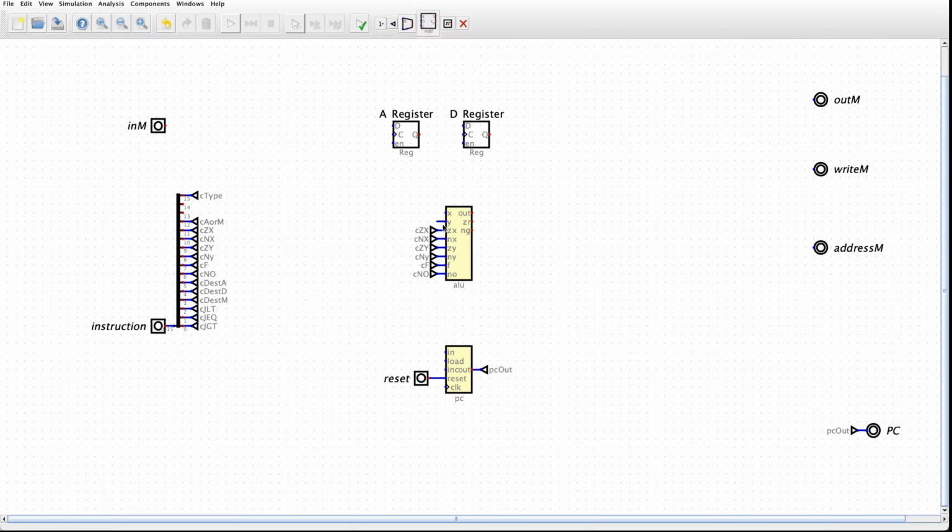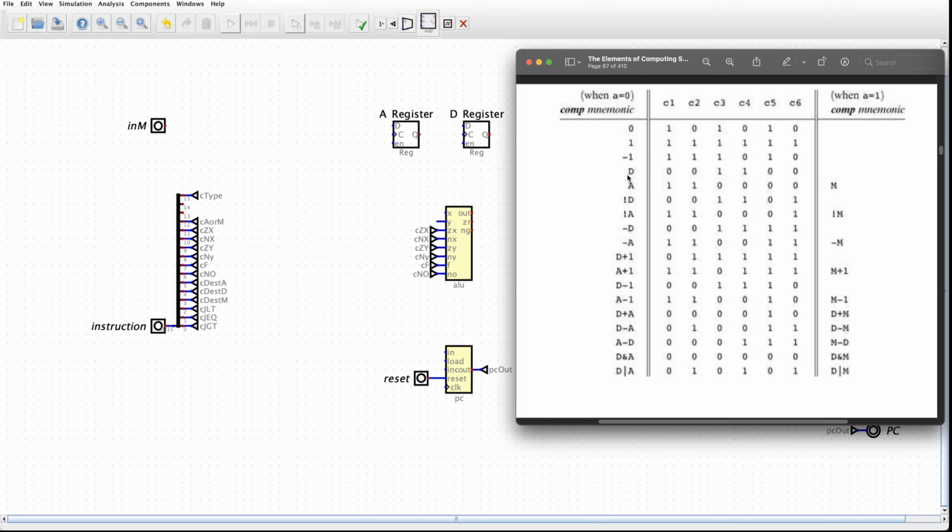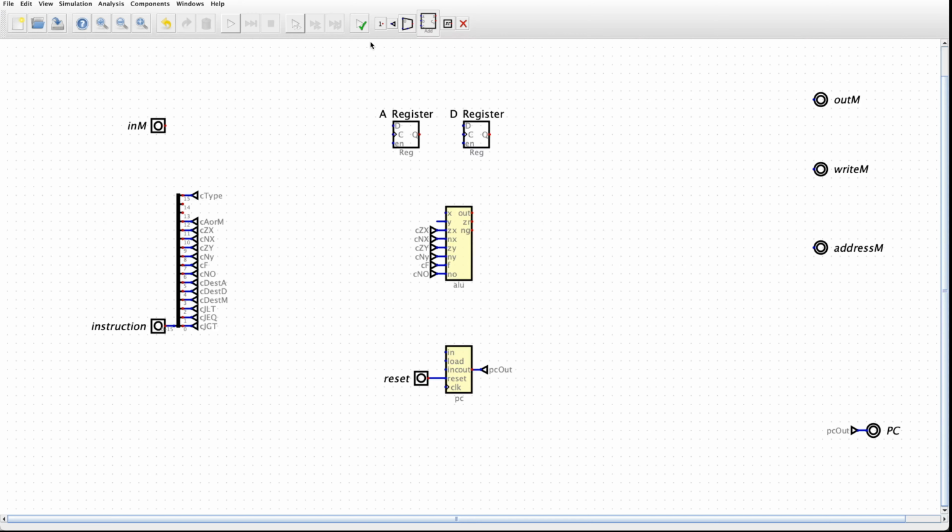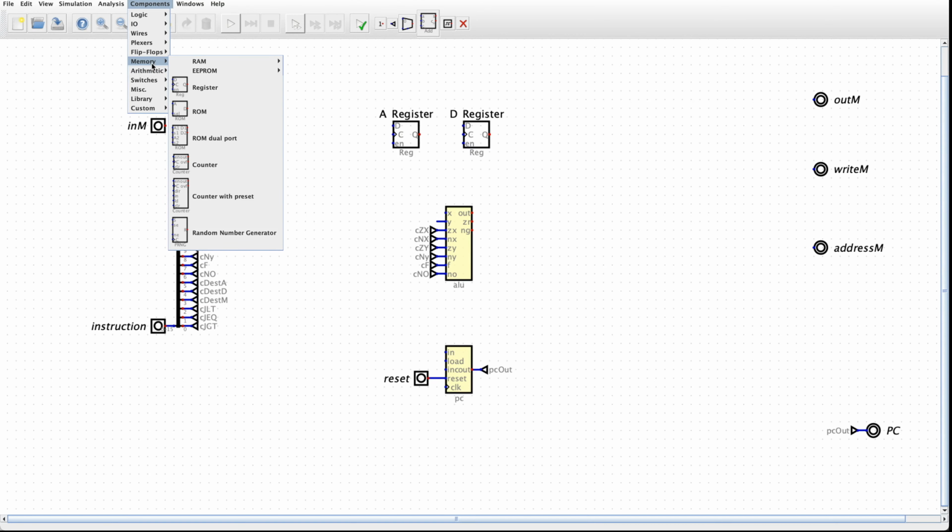So whatever value comes into X, we're going to be ANDing with Y, which is the same thing as give me back whatever I put into X. So since this is the opcode for D, this is essentially the identity opcode for whatever goes into X. And since we're being told by the spec that that's going to emit D, we now know that D goes into the X input. Excuse me, I didn't mean register, I meant input.